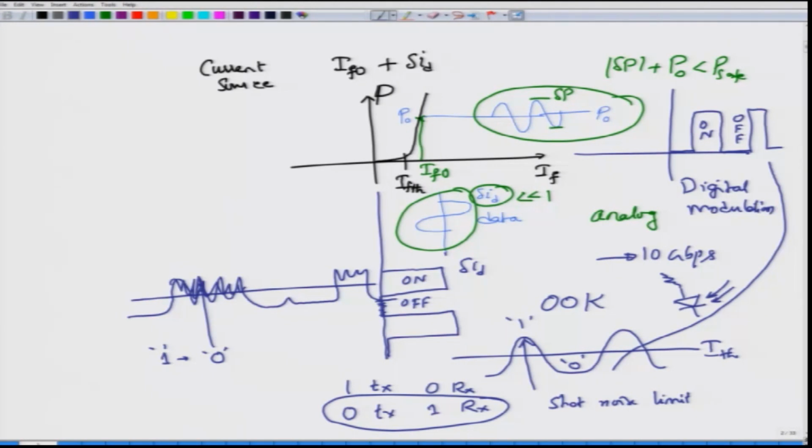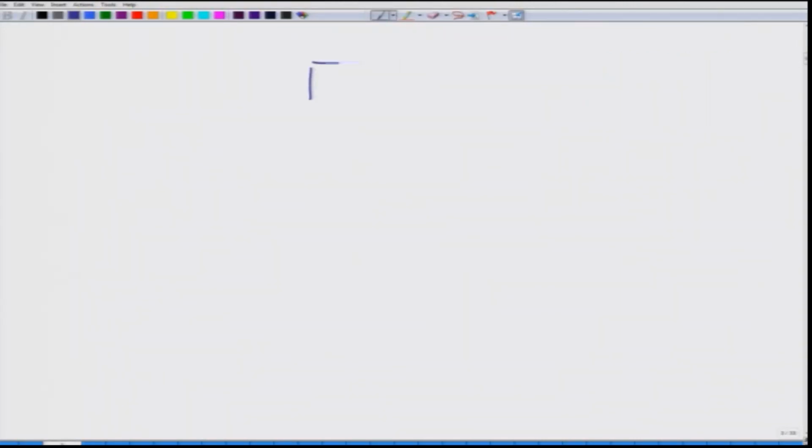transmission. So, this is the older digital modulation technique, and this type of modulation is called direct modulation, because no other device was externally used to modulate. But in practice you will have to use an external modulator, because as the data rate increases, the direct modulation of the laser cannot happen, because the laser has all those time delays that I just spoke about, in the form of carriers being recombined, carriers being moved from one band to another band, and collection of those carriers, light and all those things. So, the rate at which you modulate will not be possible by more than 10 gigabits